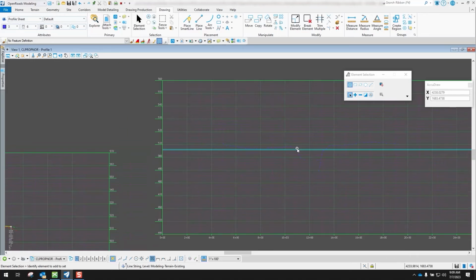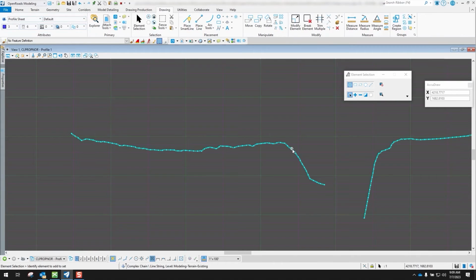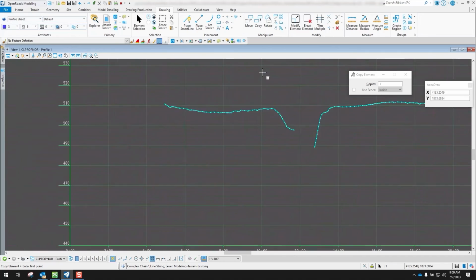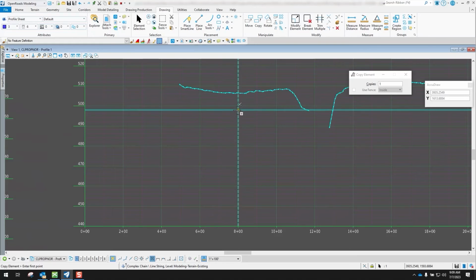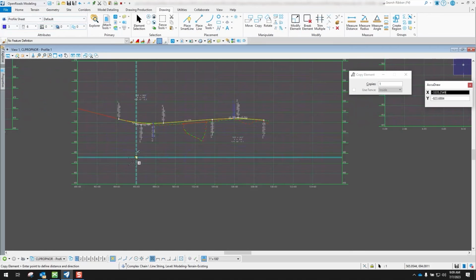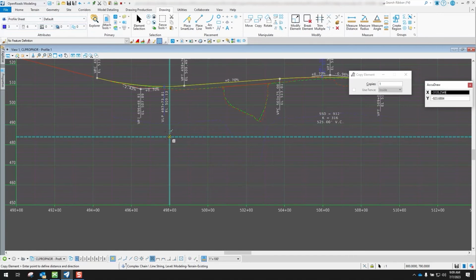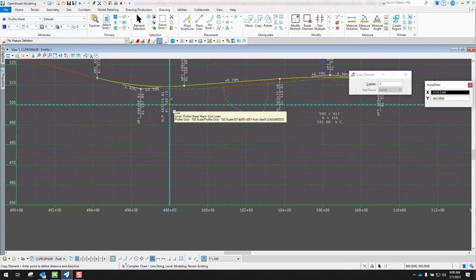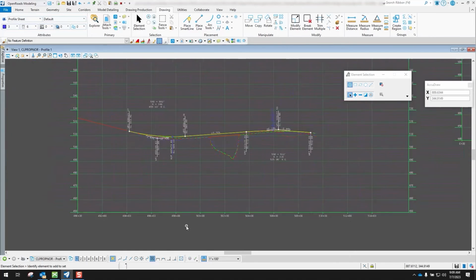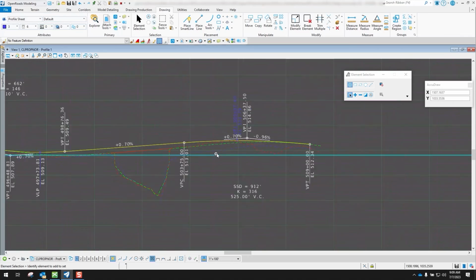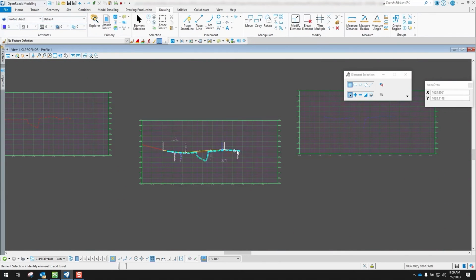And then you can do the same thing to this one right here. Select it. Copy. 8 plus 00 at 500, which would be right here. Left click to accept that snap, and then go down below here and do the same thing. 498 at an elevation of 500, which would be right there. And once it's done, I'll go ahead and right click to reset it. And now we're finished. So now you have those particular left and right 30-foot offset profiles over top of here.